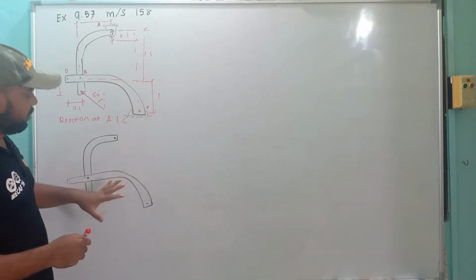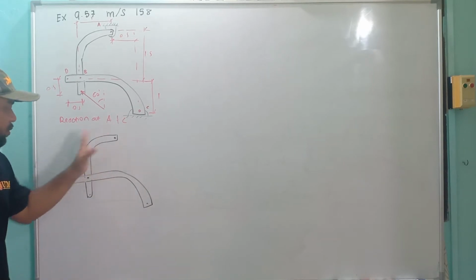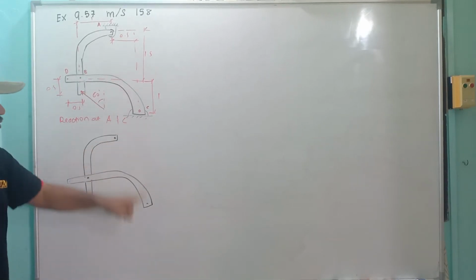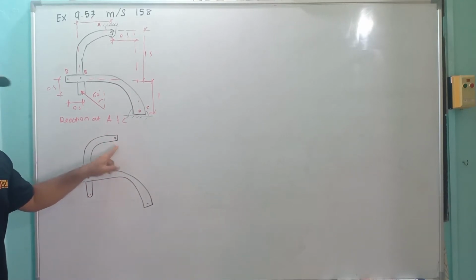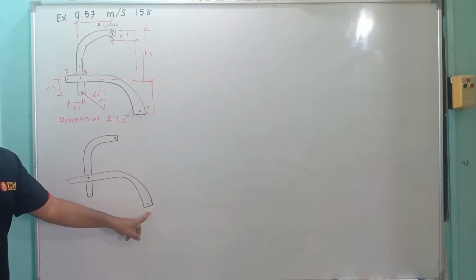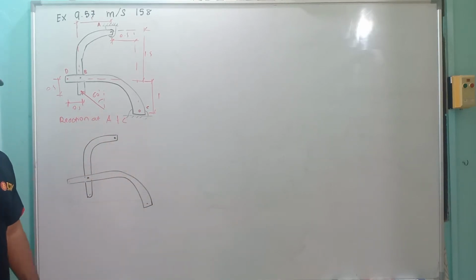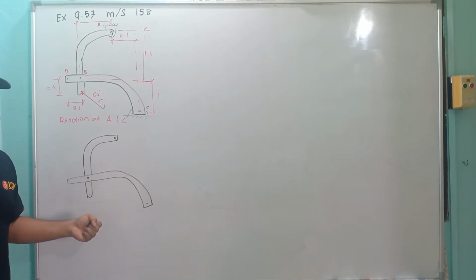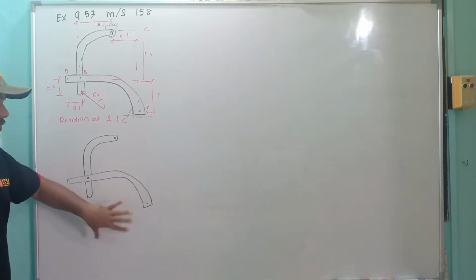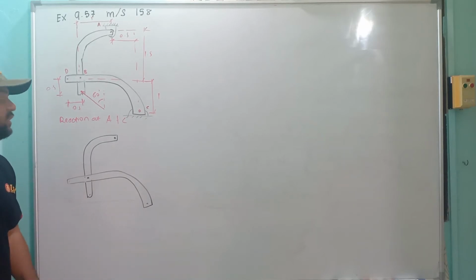A and C. So of course, I will start by using the overall free body diagram. I will not go one by one first because it involves these two points, one here and one here. If I'm using only this part, I can solve only one. If later on we cannot solve using this one, if there are too many unknowns, we can go one by one later on. But we better start by using this overall free body diagram first.